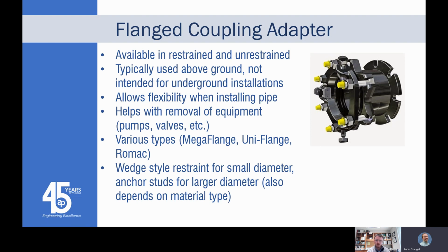they are restrained, and most of the time I think they hold, but I have seen them blow off a pipe. We had one on an air vac valve. It was a pretty big air vac valve, but they had a large amount of air get into the system. And then once all that air hit this air vac valve that was held onto the pipe with this restrained flange coupling adapter, the momentum of the water hitting the valve and closing the valve after all the air had gone through